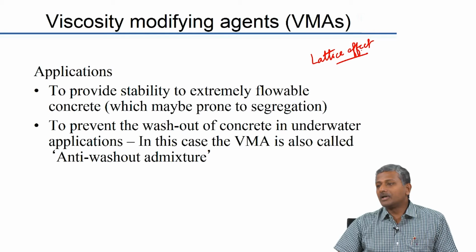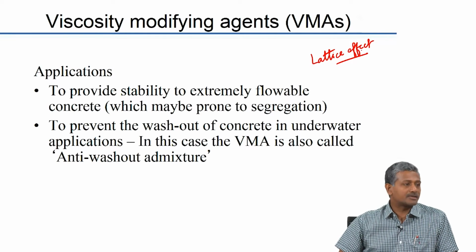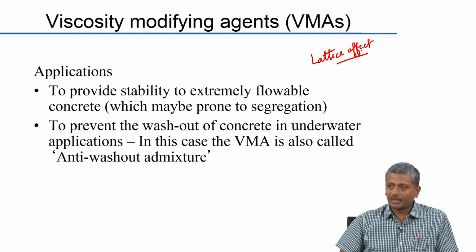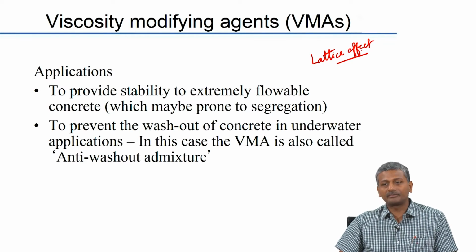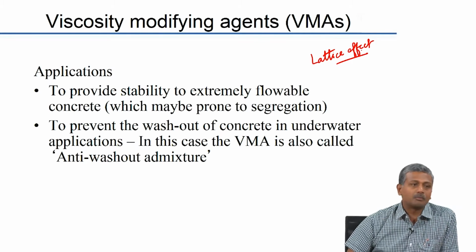Okay. But when you go to concretes that are more specialized, which have less aggregate and more cementitious paste, there the chances of settlement of the aggregate are large, and that needs to be avoided by ensuring that you have sufficient viscosity in the paste to eliminate or reduce the extent of settlement of your aggregate, and that is brought about by viscosity modifying agents.